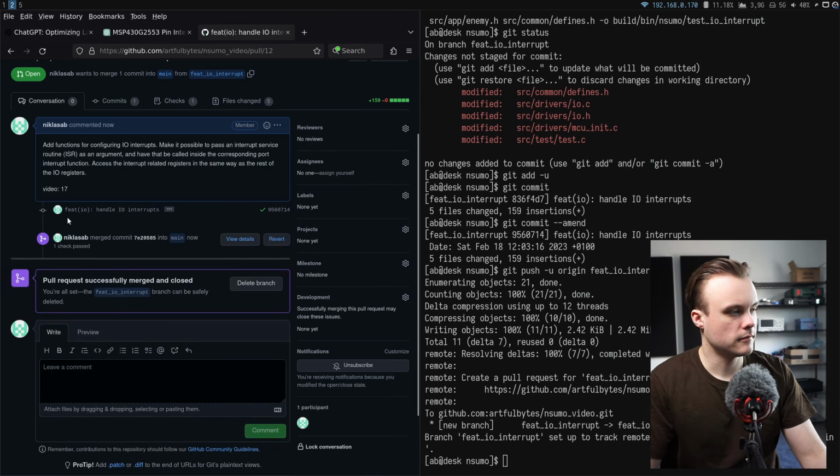Bam. The last thing I'm going to do in this video is to increase the clock speed of the microcontroller from the default 1 MHz to 60 MHz. The microcontroller I'm using in this project is actually aimed at low power applications, and as such it has many different clocks, and you can configure them in different ways to trade off performance for power consumption. But for my application I'm just going to configure the microcontroller to run at its maximum clock speed,